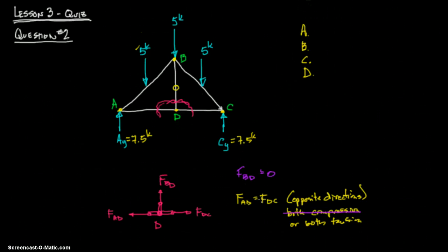So just so you see that coming. So we know FBD. This is about all we know. And I'm going to go ahead and move on right now because I said quite a bit, actually. So I'm sure the answer is somewhere in that explanation I just gave. So let's go on to A. The force in member BD is 0. Okay, BD equals 0. We said that. So that's correct. And members AB and BC should be designed for combined bending stress and axial. Yes, because they're not loaded at a panel point or at a joint. So yes, A is seemingly the correct answer. That's exactly what I said, and yes, that's perfect. But let's go on and make sure that something's not more perfect, which I don't think there's going to be.